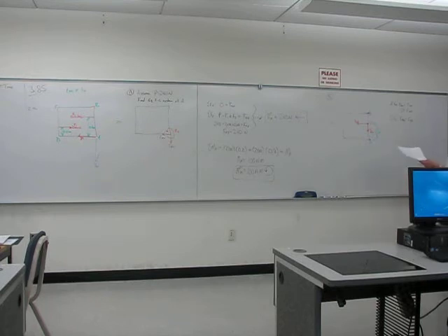Well, we already solved for FAZ, it was 240. So again, you combine the two components here, and what you're going to find is that FE is exactly the same as FA. It's 240 newtons going in the positive Z direction.